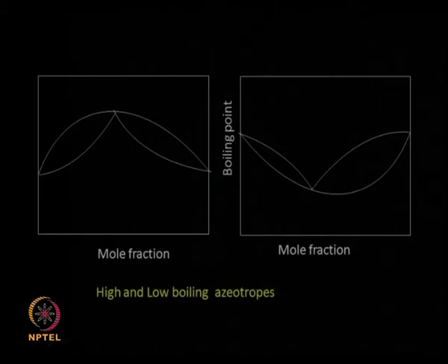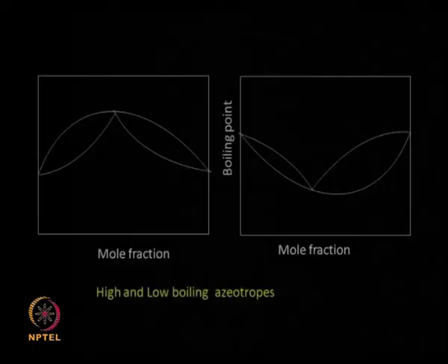So what do you do if you have azeotropes? There are different methods. You sometimes change the pressure condition so that the azeotrope may go, or you sometimes add a third component so that it breaks the azeotrope, and nowadays we are resorting to even membrane type of situations where we can break azeotropes, because membranes do not work based on vapor pressure, membranes just work based on either size or molecular weight, solubility and so on actually. So there are pervaporation membranes which we talked about long time back.